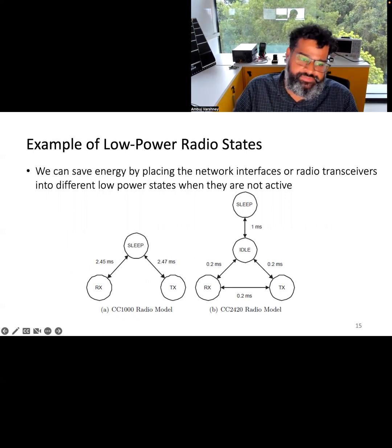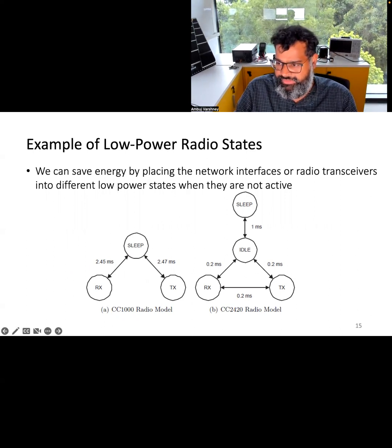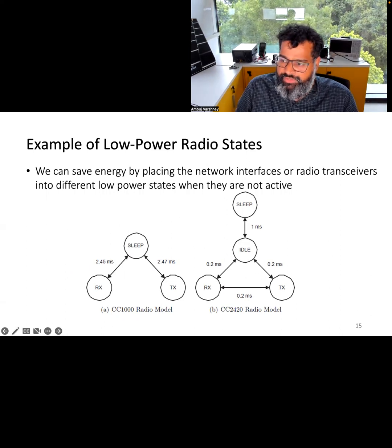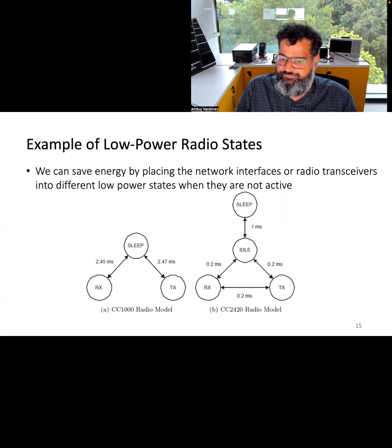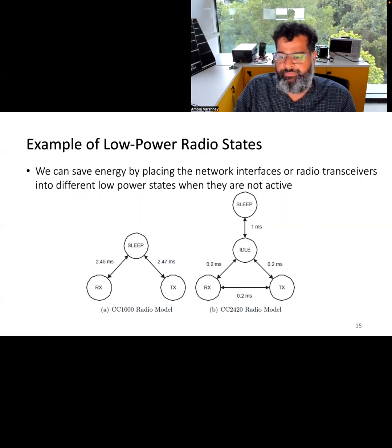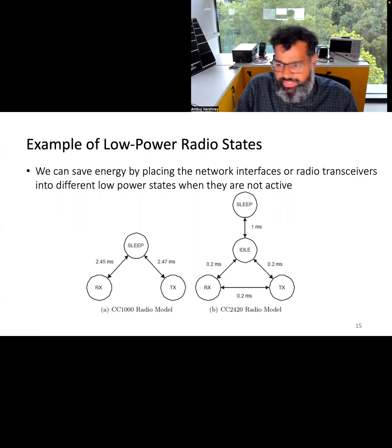And of course, the power consumption is very different between the states. Sleep is much lower in power consumption than the idle state. And to maximize the battery life, we would want to keep the radio in a low power state as much as possible, and only switch to a high power state when it is absolutely required.